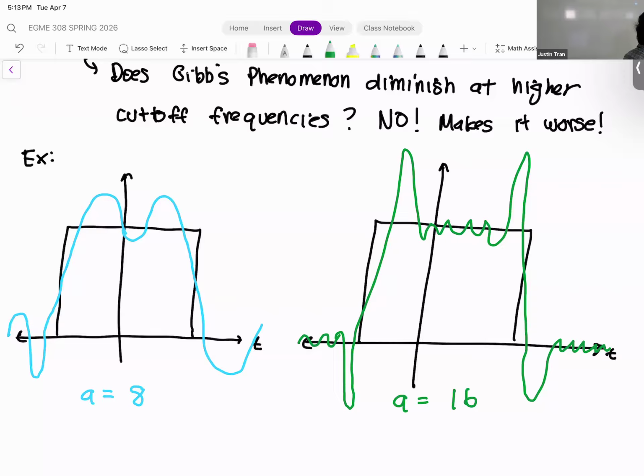But when you do set your cutoff frequency to infinity, the Gibbs phenomenon magically goes away. It is a very interesting phenomenon, and practically it's not something you would observe, because you're never going to make an infinite summation of Fourier terms. But it is something to be aware of as you work with Fourier, especially with choppy, discontinuous signals.